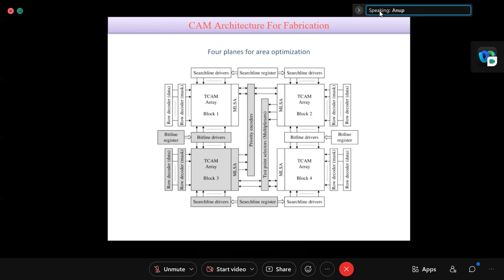Like the carry look ahead adder circuit: we design it so that we can see the carry ahead before the computation. But if we make it for 8 bits, then the carry look ahead circuit itself will take more delay and more power than the ripple carry adder. So we have to go for optimization everywhere. Okay, so these are the macros actually.